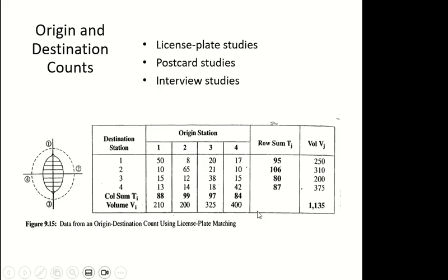So these are from the field counts. The field count is just taking total vehicles entered, total vehicles exit, vehicles or people, total for each area. And obviously it should be in the same time period. So for area 1, they recorded on the field that 250 people entered area 1 total. Okay, now the total I am getting for the sample and the total I have in the field, you can see they are completely different. For area 2 again, and the same thing for exit as well. So from area 4, they recorded 400 people were exiting from area 4, and the sample only gave me 24. So there's a lot of difference.